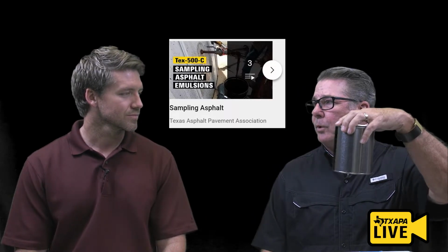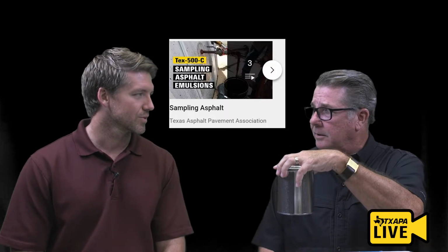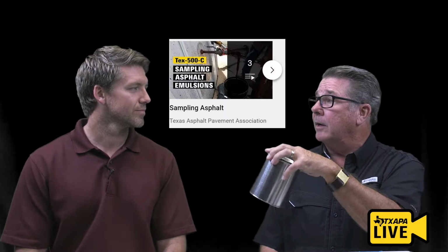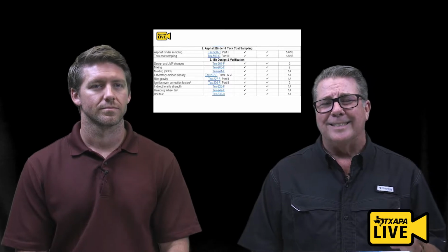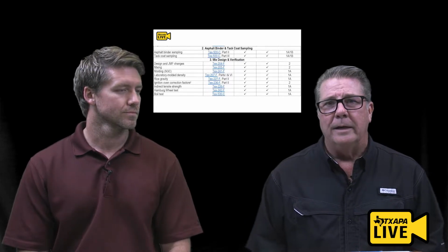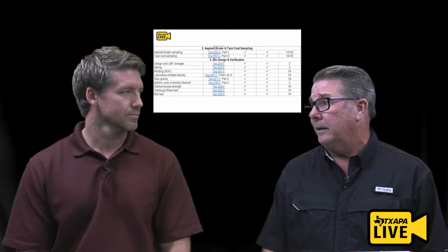You don't want to test a failing production sample and then have to second guess the rest of your material. Right. So with our hot AC sample, I'm the contractor and I'm pulling the sample, you witness it, and then after it cools down, you take immediate possession of it. Correct. And if it's going to be tested, you send it off to Materials and Tests to have it tested. Correct. But this sample should not be laying around in the storage farm or anywhere else. Once the QA individual takes it, it's their sample. Chain of custody is very important. Chain of custody. We're going to talk about chain of custody quite a bit throughout this because not only is the sampling and the testing real important, it's how that material is handled and who is handling it.